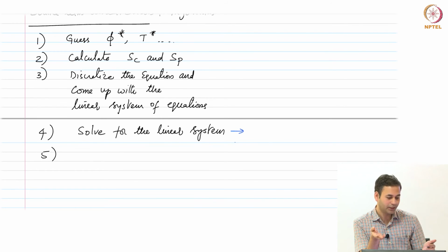As a result, we are now introducing an iteration on top of the iterations we might have had in step 4. If you had used Gauss-Seidel, you are doing iterations in step 4. Now I have another iteration that I would like to call an outer iteration, which is coming out because of nonlinearities in the problem, because we have linearized the nonlinearities.